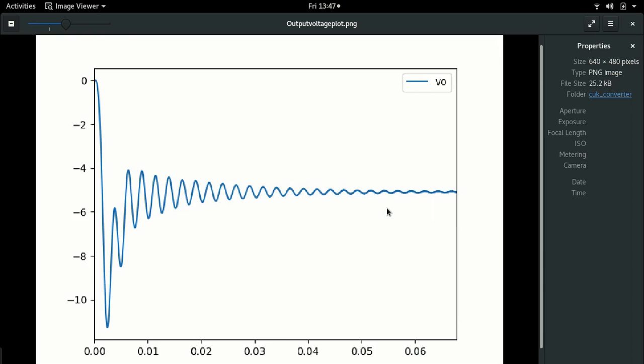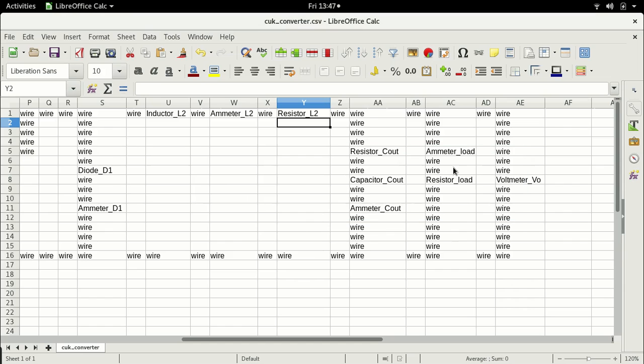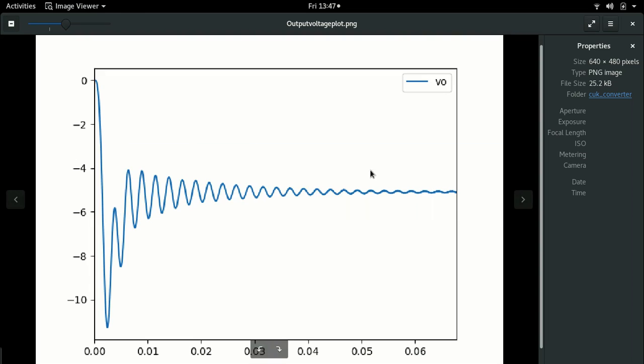So we are still measuring a voltage, whereas the output voltage we measure is still with respect that the positive polarity is above. This is because it's important to show that the output voltage is negative, right? We cannot hide that fact. If we reverse the polarity of the voltmeter, we'll get a positive voltage, but that's actually misleading. That gives you the idea that the Cuk converter doesn't invert the voltage, but it does indeed invert the voltage. So this result is okay.